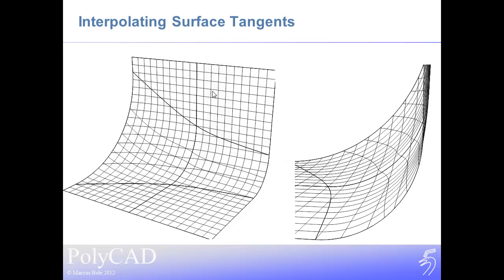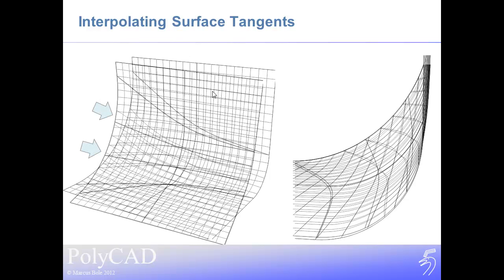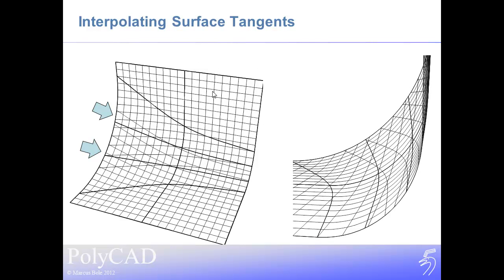So this can be illustrated on this example here, where we generated the patches over that edge, and we see that that surface tangent has slightly misestimated the angle of the surface along the edge, and we get a small bump. Now, unless we interact directly with the surface tangent, the only way we have of really resolving that problem is to subdivide the surface along there, introducing one or two curves, as this example suggests. And you can see that the lines are now much more fair along that edge. However, we didn't really want to do this, and having done this, we now have almost double the number of patches along here. So refining the surface in this way to, so to speak, correct the software where it's misestimated it, can be a particular issue that ultimately generates us more surface than we really want.